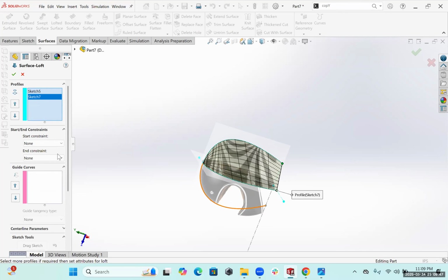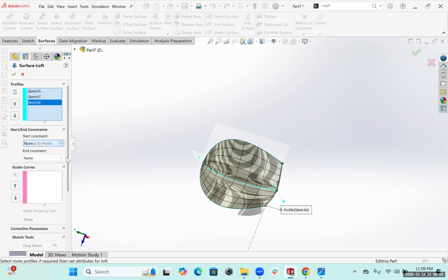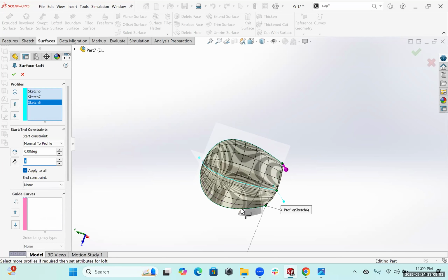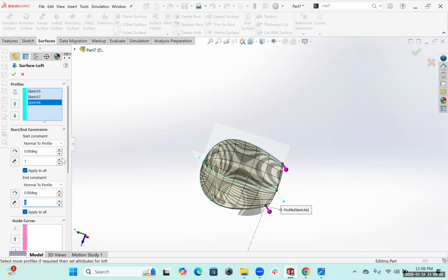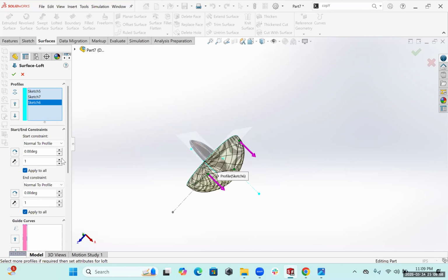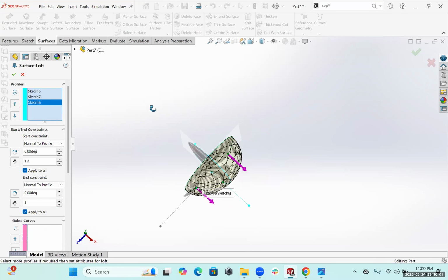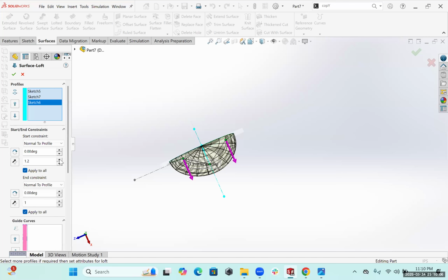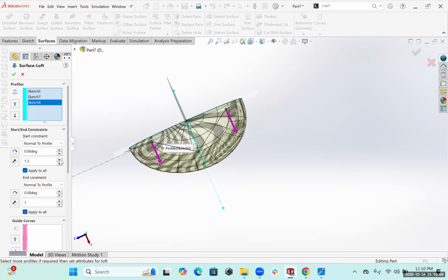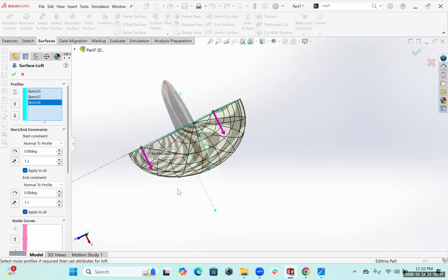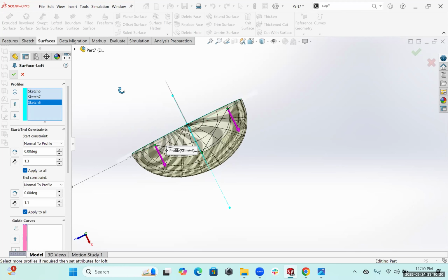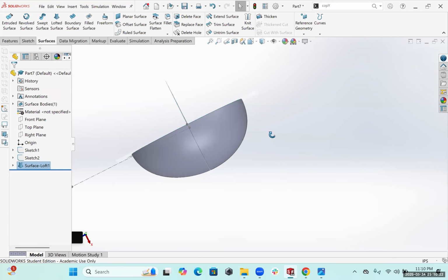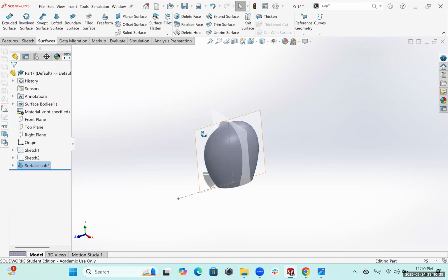Here we go. Now once we set up the arrows, they're a lot easier to see. This is the arrow for the back, and this is the arrow for the front. So when we go up with the number, this is the back side. That's getting wider. The front, I'm going to try to stay. The back, I'm going to do 1 point, maybe 1.3, and the front maybe 1.1. So it's slightly more curved on the back side. And press OK. So now we have like a nice half dome here.